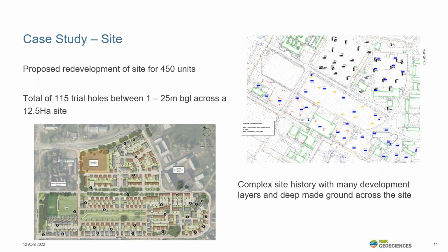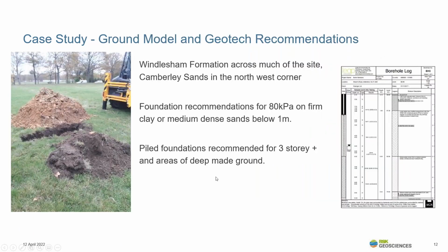So we've carried out extensive pre and post demolition investigations with a total of 115 trial holes between 1 and 25 metres across the site. The site's a former barracks and has a complex site history with multiple development layers. It's underlain by the Windlesham Formation, which comprises interbedded sands and high plasticity clay across the majority of the site.